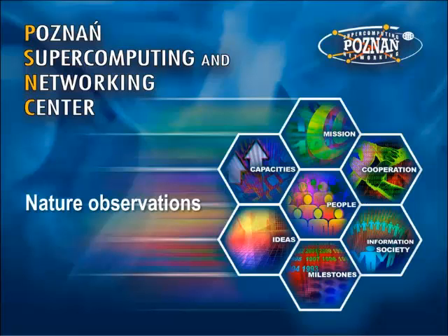So, for example, we have a Sony projector, which has 4 dual links, in fact, which is more or less the same as 3G. So we even have 8 links for 4K. It's a technical problem, of course, because you have a lot of cables, but just to provide the best quality and the best resolution, you need to use 4 3G SDI links.